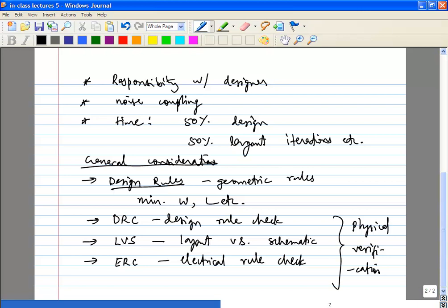It's going to blow. The gate will blow, typically, because that usually has the lowest breakdown voltages. And similarly, if you connect a thick oxide transistor or the IO transistor to a low power supply, what happens? You may design it for a certain resistance or a certain GM, and your VGS is going to be different from what you wanted to apply.